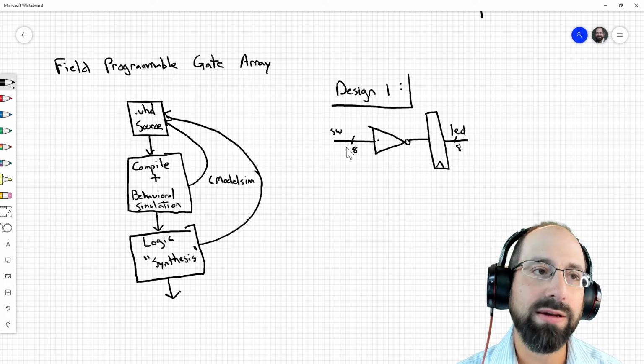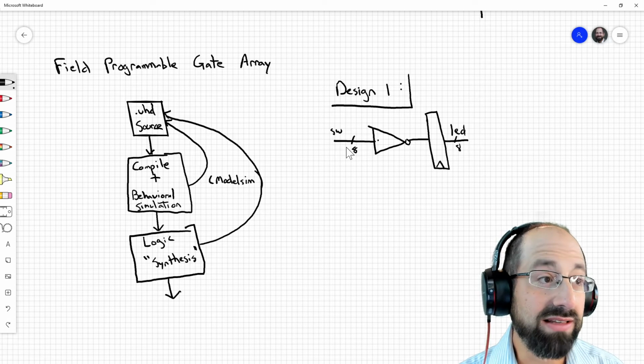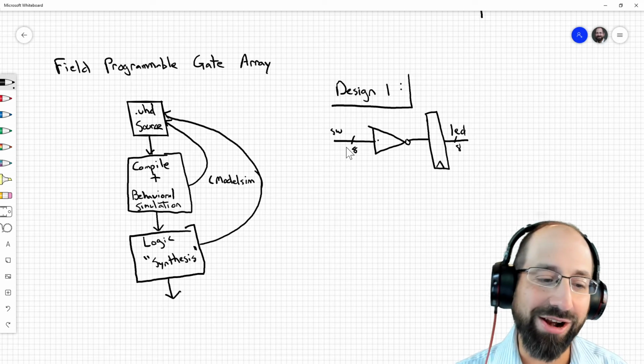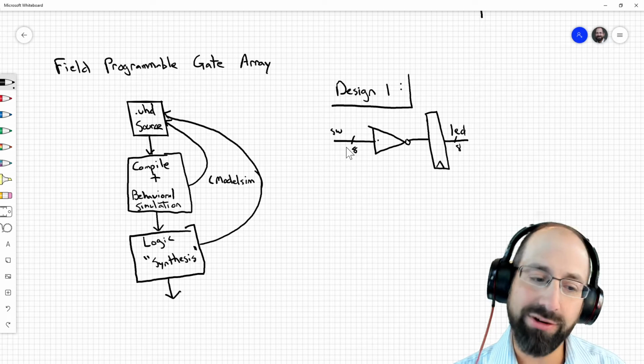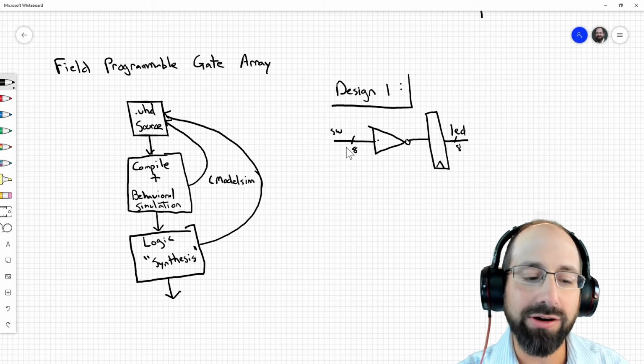Just like in ModelSim, certain messages it will tell you will actually be listed as warnings, but they're very clearly errors, right? If you get this warning, your design's just not going to work and you should stop, even though it's not strictly elevated to the point of an error. Same with ModelSim.